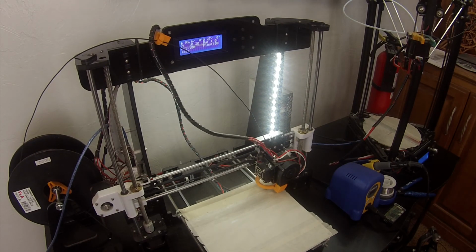And then you would again repeat that Z leveling process to adjust the screw until what reads out as 0 Z height on your screen is actually the point at which the nozzle starts making contact and dragging on the paper. You want there to be a little bit of height between the Z0 and the 0 of the bed, so that way whenever the nozzle prints the first layer, it basically presses the plastic down, it smushes the plastic a little bit onto the surface to get good adhesion. You don't want to be 3 hours into a print and then your print comes loose on the print bed and skitters across, because that ruins the entire thing. You fail the print in that case.